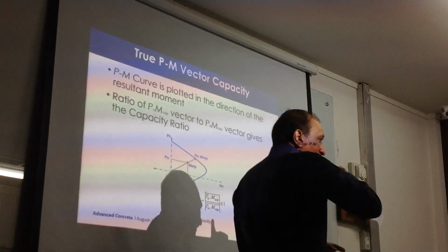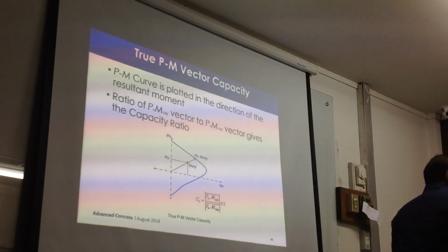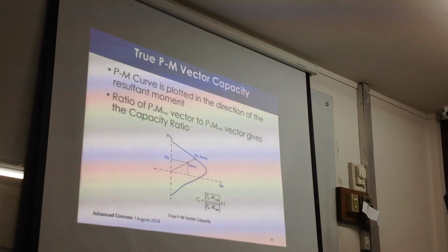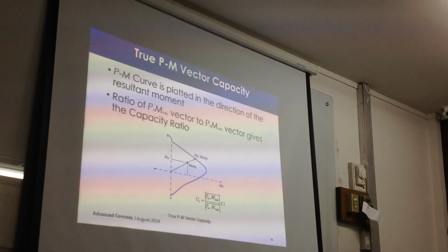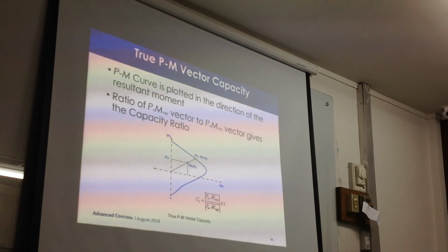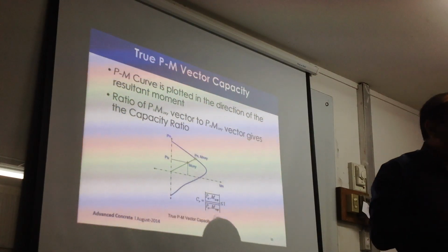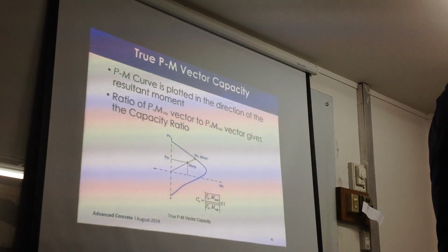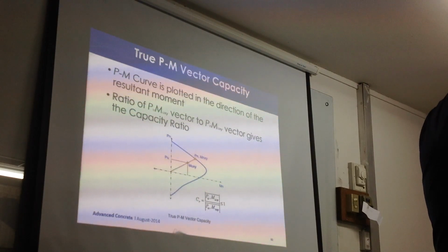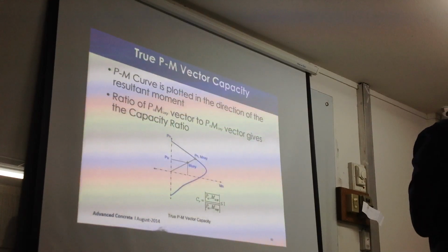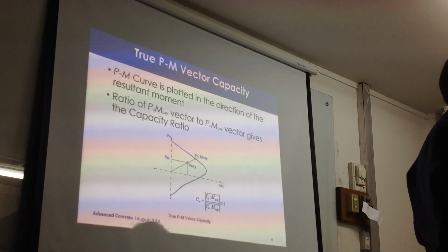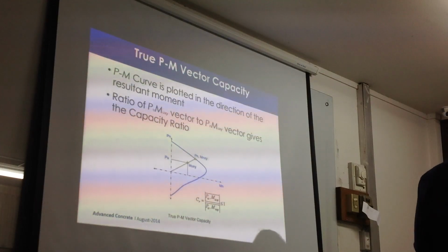You divide the surface into triangles, lots of triangles, and then you check the intersection of each triangle with that arrow. And if the triangle intersects, okay, fine. So the surface has to be meshed into small triangles, and every triangle must be checked somehow, right? And then the problem is, this is computers, there are 4 triangles meeting at one corner, let's say, and the vector happens to be passing through the point of that intersection of 4 triangles, which is possible. And none of the triangles will say that this point is intersecting me.